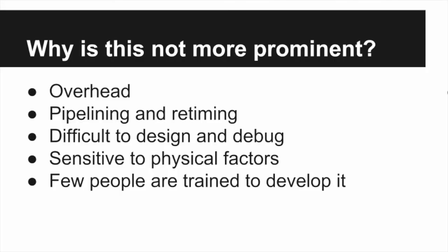With all the apparent advantages to asynchronous design, and the fact that asynchronous circuitry has been around since 1989 and the idea for it has been around since the 1950s, it begs the question, why is this technology not more prominent in the world today? One of the disadvantages to asynchronous circuitry is that it turns out the improved performance talked about isn't quite as improved as originally thought. This can be due to the overhead that is required for asynchronous circuitry.